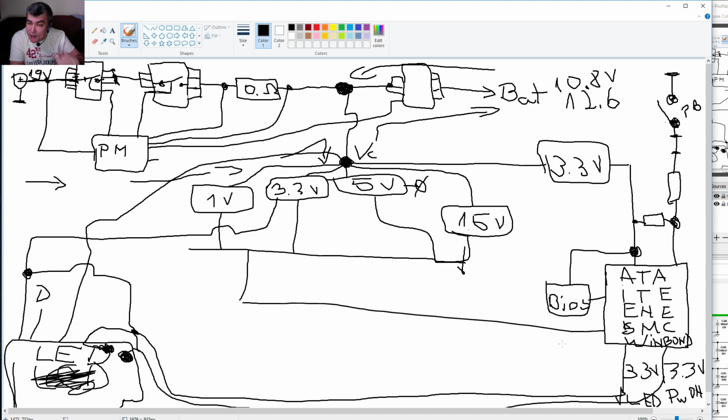If the board passed the test, you probably have a ribbon cable issue or a screen issue, but not the board. So that's the first thing when you check a laptop: see if it has light or not. That's very important, because based on this, you can make a diagnosis.